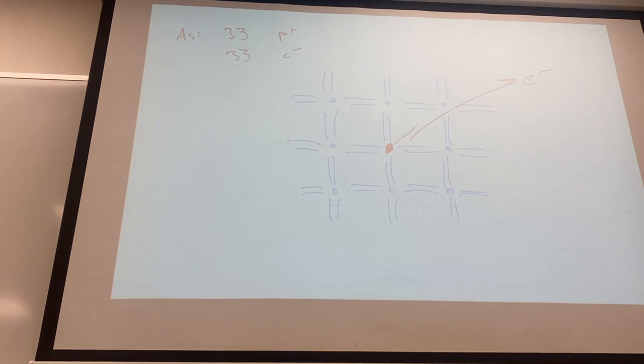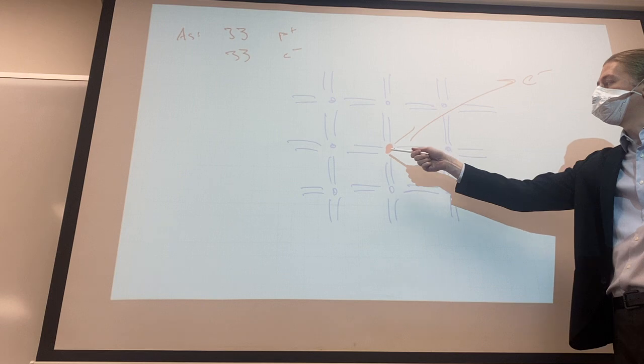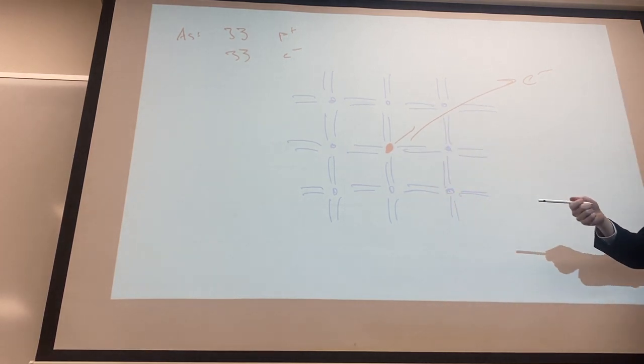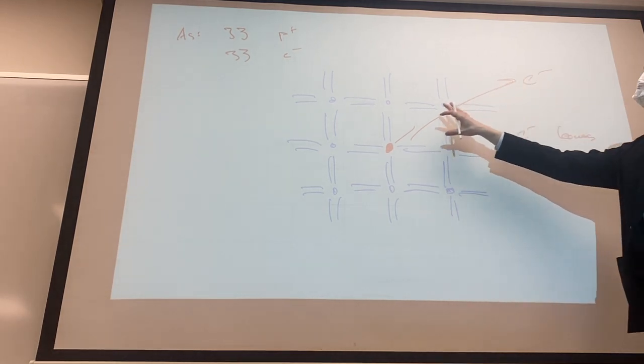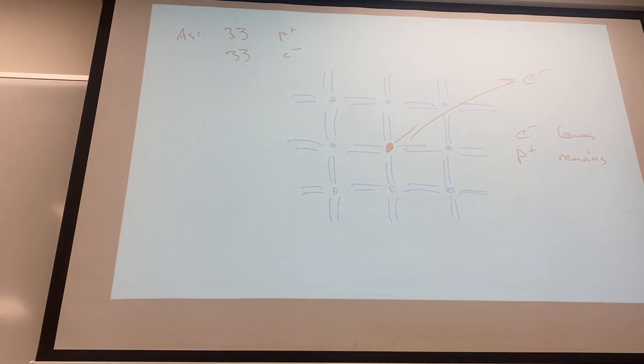But when one of those electrons takes off, what we're left with is a fixed-in-place extra proton that can't go anywhere. Meaning that this entire area, if you had this pattern repeating over and over and over again, you have a net positive charge. The electron leaves, but the proton remains, leaving this whole area positively charged. Now at equilibrium, you would expect that maybe an electron would eventually wander back over here. But in electronics, if something's biased, if current is flowing, if a voltage is applied, that's not equilibrium.